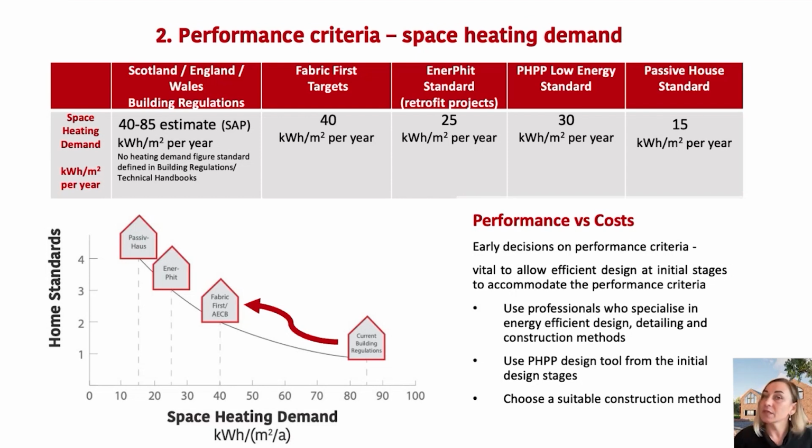So the second tip is to use professionals who specialize in energy efficient design. And I'm not talking here only about architects. Structural engineers have a great impact on the design of the structure of the house. They will potentially be specifying the steel supporting structure that can interrupt your insulation levels.